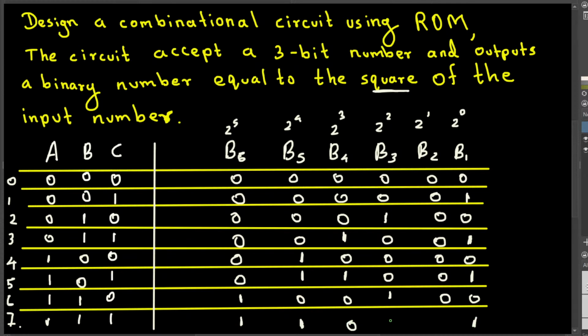Okay, that's it. Now we have to see whether we can simplify this one, because we want to build the circuit as simple as possible. So to look at that, first as I see, this whole thing is 0. So you can connect the B2 to the ground, because this is not necessary. We don't need that.